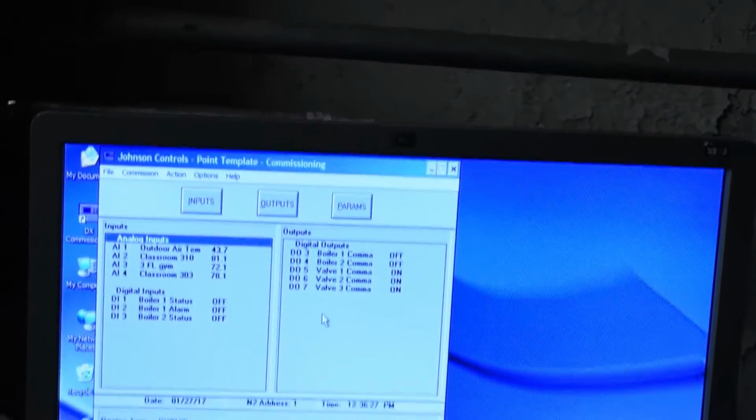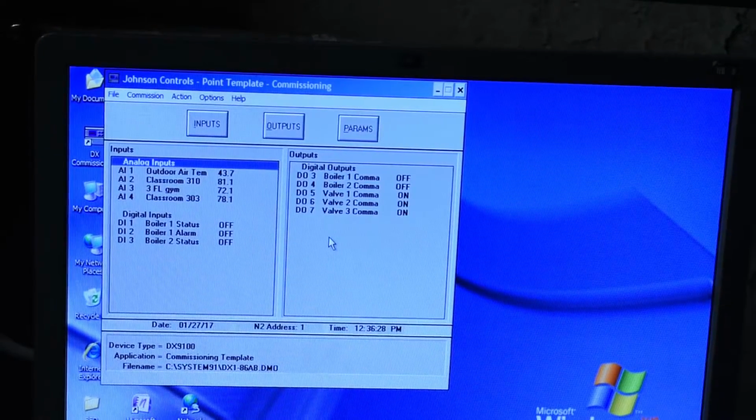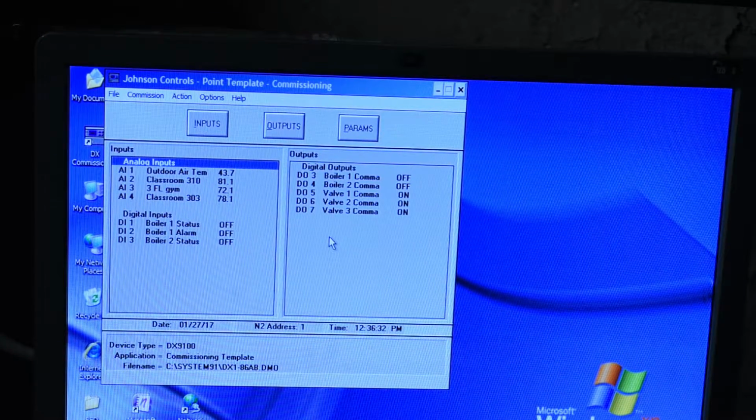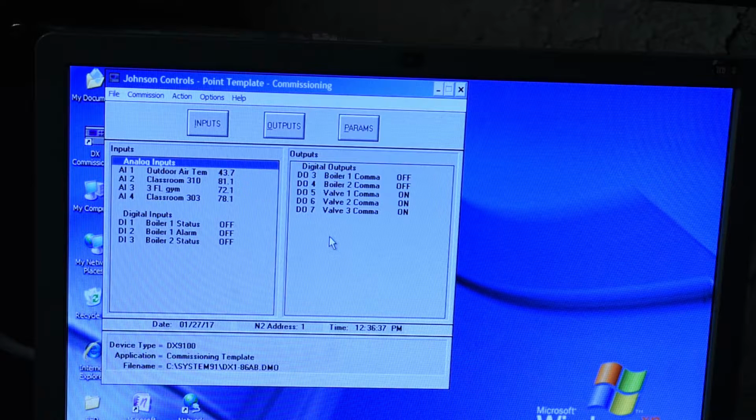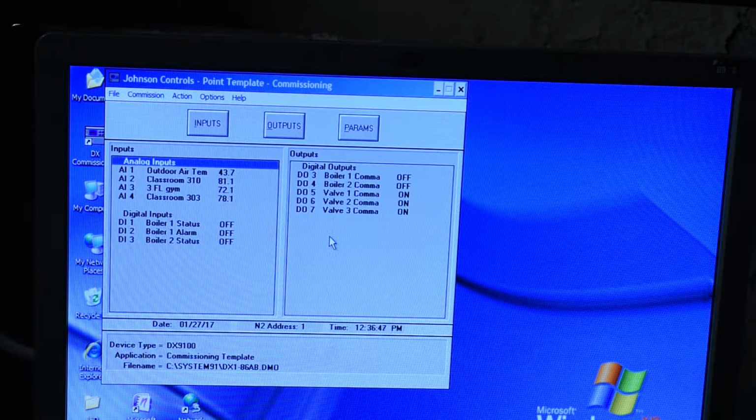This building has been receiving overheating conditions, meaning in the mornings it's almost up to 98 degrees in the classroom, which is really over not only the set point of 75 degrees, but very overwhelming to work in that type of environment. We basically want to maintain an environment during the winter time, a temperature range between 68 and 77 degrees.